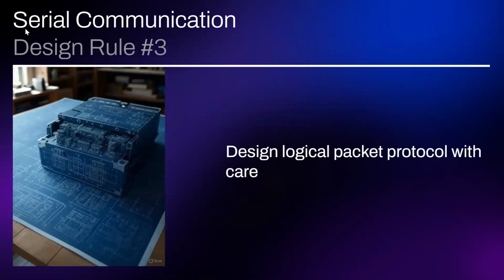So design rule number 3: design the logical packet protocol with care. Pay attention to it. Don't just run in and do the character by character thing. It also should not be an afterthought in your design process if you're designing a serial protocol.